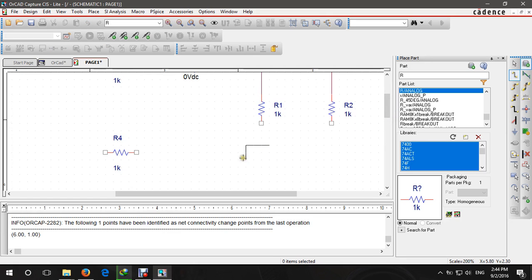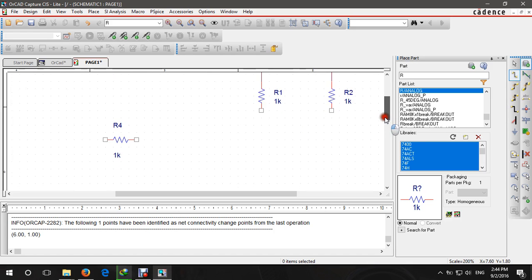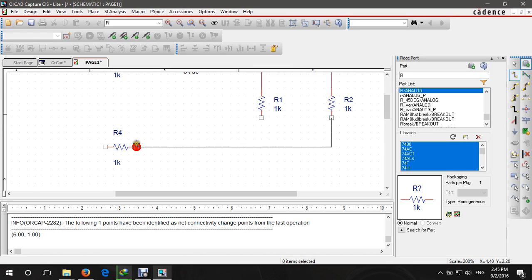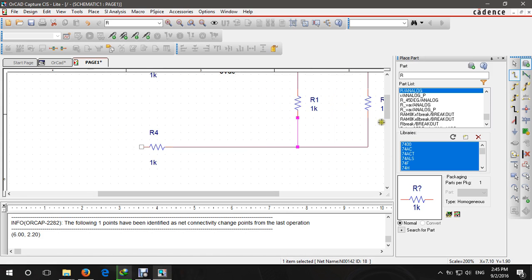Now it's a smart software. So when you press escape, it obviously clears it and deselects the wire tool, so you just press the W key again and it appears again. There you go. So yes, it is smart, so it's not totally up to you. It is a bit of an intelligent plotting software or feature. As you can see, if I do this and if I just go here, for example, it connects it like how you would want to connect it when drawing a circuit. Then I connect that to here, cool, and let's just move that over a bit.